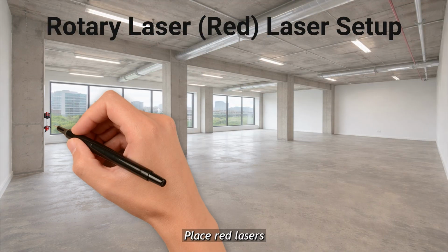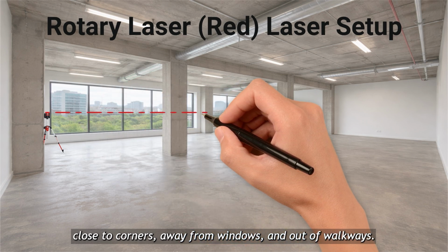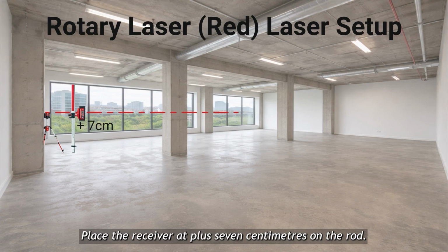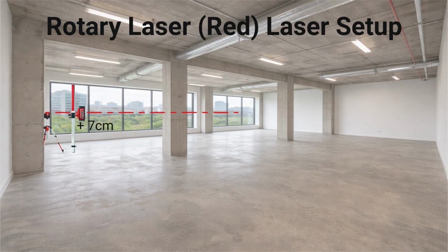Place red lasers close to corners, away from windows, and out of walkways. Place the receiver at +7 centimeters on the rod. Adjust until the receiver indicates 0 with a steady tone.